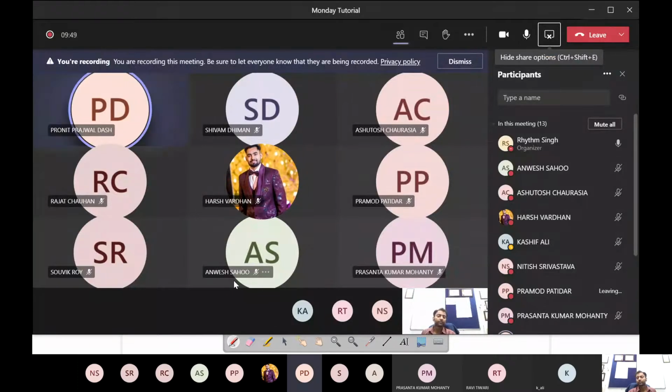Sir, is the dummy load connected all the time, or do we connect it only when the load decreases? As I said, it will depend upon what type of control you want to achieve. If you just want unidirectional control, that means the load is at a constant value, and when the load is dropping you don't want the frequency to increase, then you can have no dummy load in the base case.